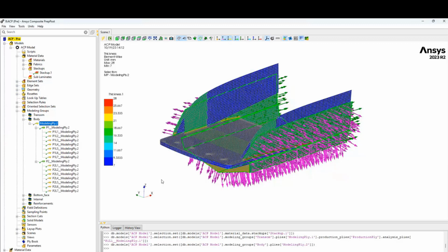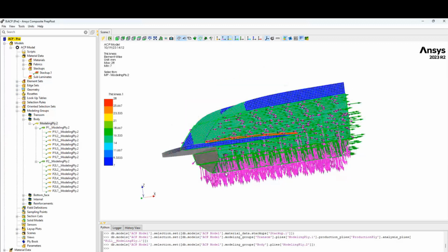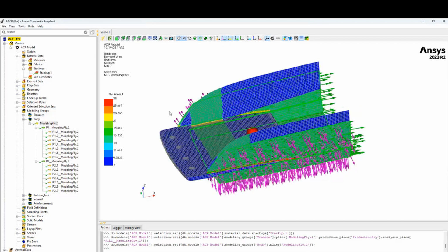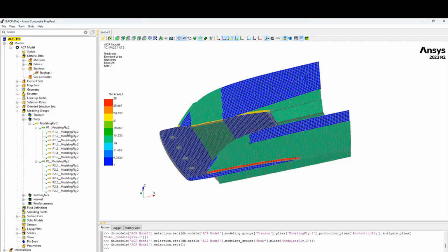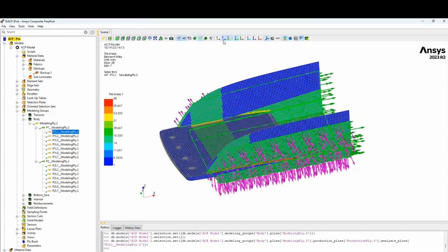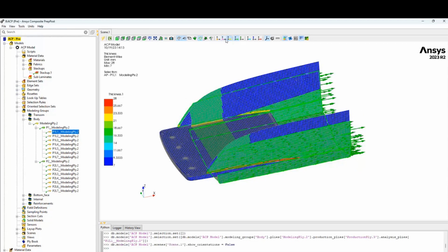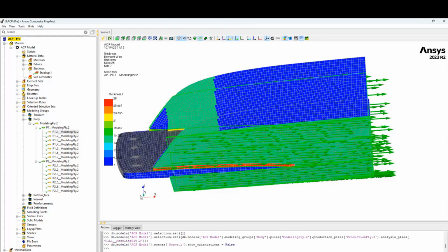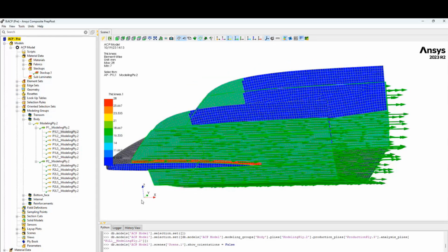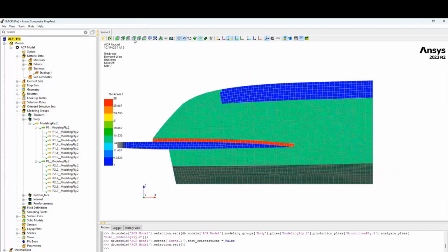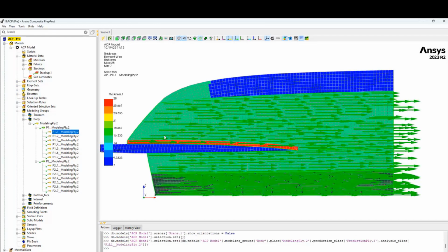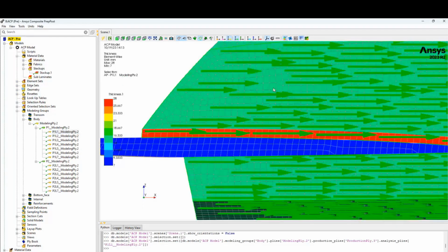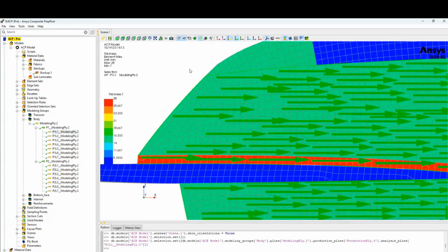We can see we have any of these here. Once the composite layup is constructed, for example, I am going to hide that, and I am going to show this. Let me orient the view like that. Okay. For example, here we can see the green vectors, which indicate the orientation of this layer.